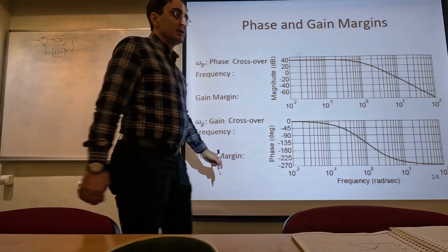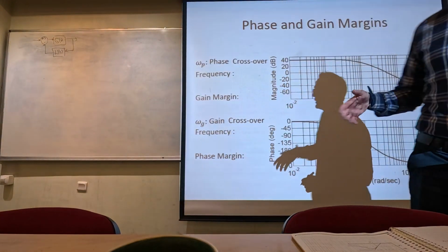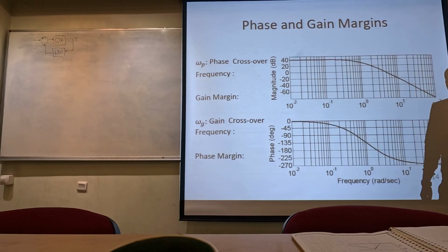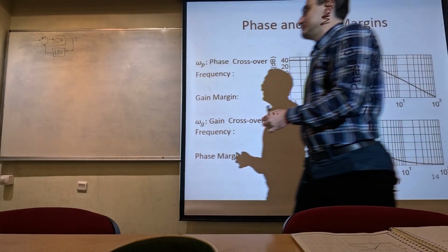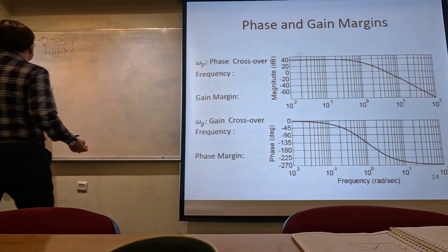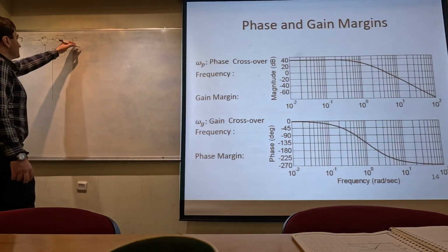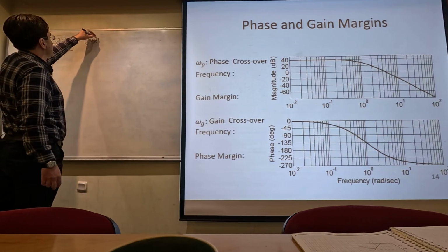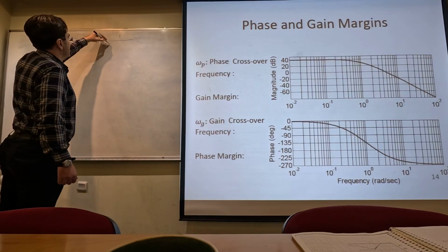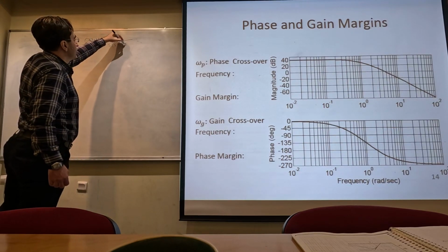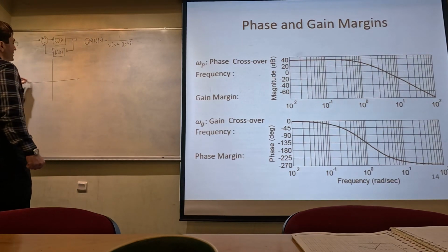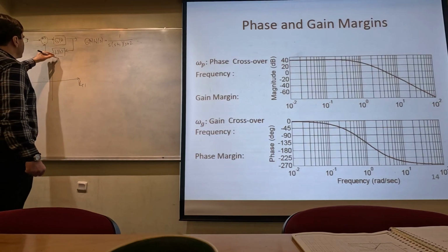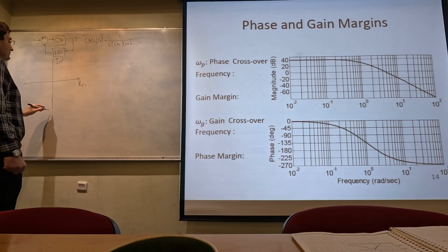We can actually analyze such a system by using its Bode plot. Okay? So here, you might remember that sometimes if G(s)H(s) is, for example, 1 over s(s+1)(s+2), you might remember the following figure here. Its Nyquist plot looks like this.